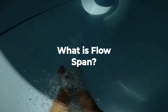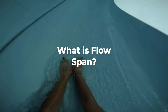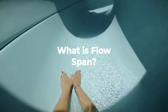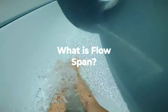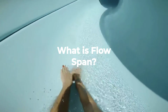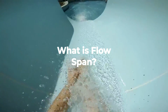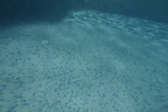So that is pretty much what you want to set your 20 milliamps to. That is different than the flow range of the device. So you might have a 1-inch mag meter that can measure 0 to 78 gallons per minute. But if the process is never going to exceed 30, you would set your flow span to 30, and that, to Paul's point, would be what the 20 milliamp signal would represent.